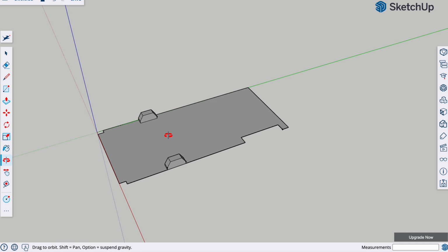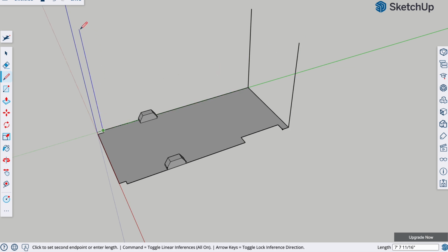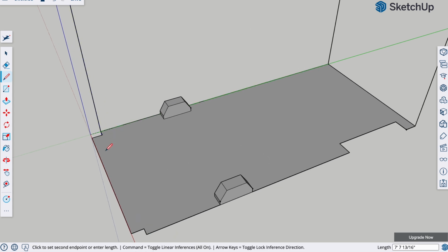So you're going to then need the vertical dimensions. You're going to click one corner, start to go up on the blue axis, and I think 79 inches might be right. So we're going to type 79, hit escape, and do that on all of the corners, and make sure you're staying on the z-axis when you do this. Hit escape after each one: 79 inches, escape, 79 inches, escape, and you don't have to see the tops of them.